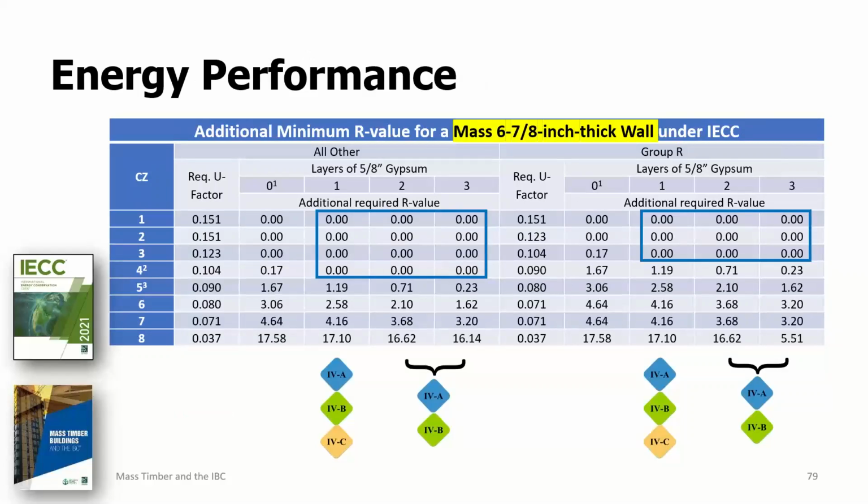So this is a mass wall. This is comparing against the last one where we said, look, if you're a 3-panel CLT, you're probably not mass, and so you're going to need some insulation. This is saying, if I make my CLT a little bit thicker, 1 layer thicker, how much insulation do I need then? Those blue squares are where technically you wouldn't need any insulation to meet the energy requirements. So it becomes a trade-off. If you want to have a little bit extra panel, you can have less or no insulation depending on climate zone and whatnot. It's the cost of the panel versus the cost of having an extra trade go in there for the insulation.